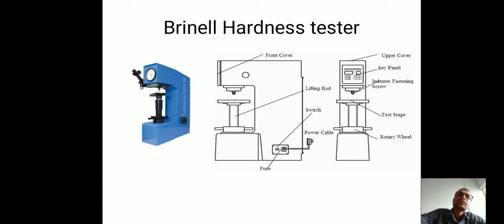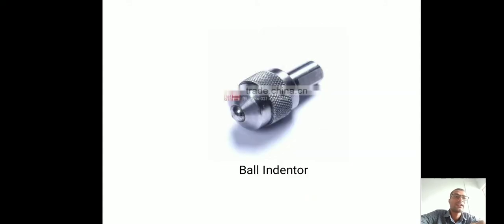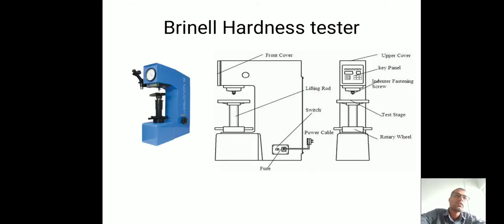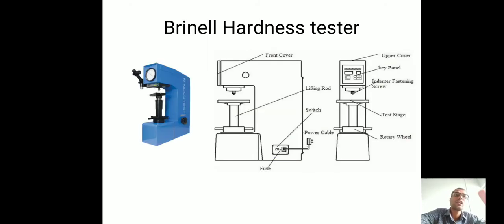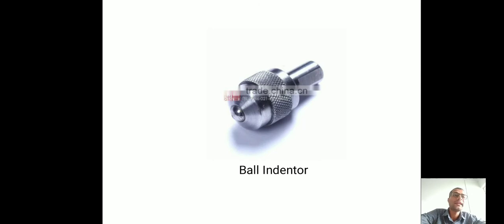So while doing the Brinell hardness test, the indenter plays an important role. So let's move towards what an indenter is. The indenter is a part that, while working this machine, moves inside the test specimen. Related to the Brinell hardness tester, always keep in mind that a ball indenter is used,